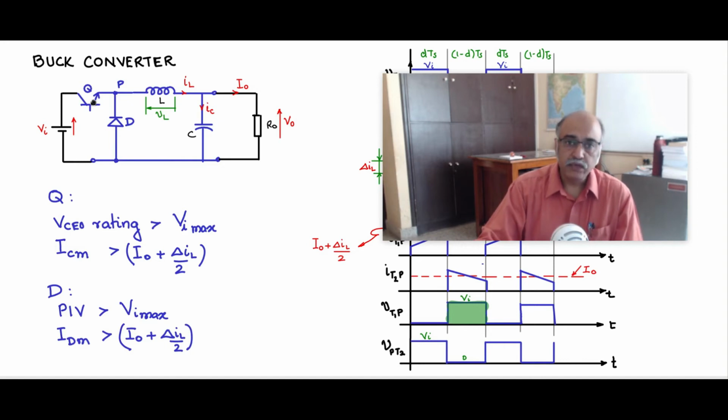In the case of the MOSFETs, you need to provide a certain amount of gate charge for it to turn on, and remove a certain amount of gate charge for it to turn off. So each of the semiconductor switches will have its own characteristics, and we will have to design the drive circuit appropriately so that you can turn the switch on and off at will.